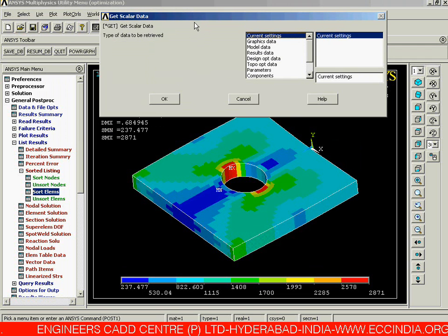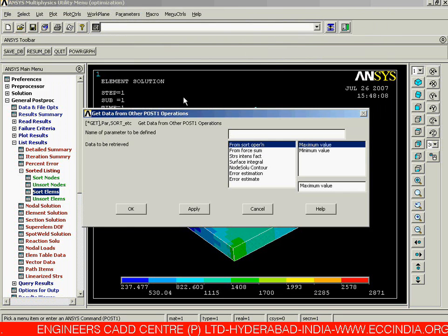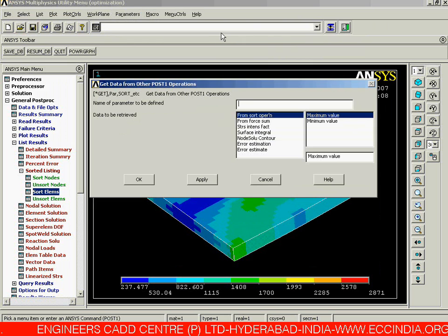So in this particular case, now we need to add the result stresses. We need to define a results data over here. Once we are going for the results data, now we need to go for the window over here. In the results data, we need to go for the other operations over here. The results data in the first window, and let us say it is the other operation over here, and then say OK.